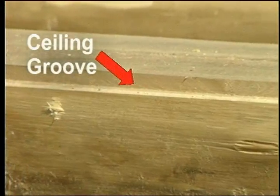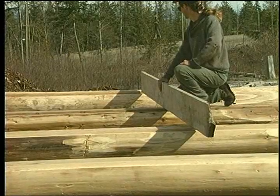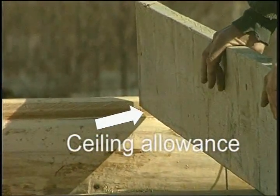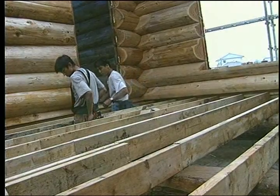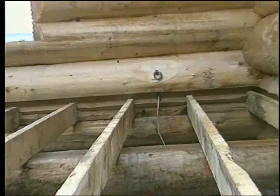In this case, you would cut a wider recess at the plate log and cap log to accommodate dimensional joists and ceiling, as well as the flooring. A recess for the ceiling material can be dadoed into the edge of the beam or a furring strip secured to the top. If the ceiling is to be decked with a planking material such as 2x6 or 2x8 tongue and groove, it can be an advantage to make a groove for electrical wiring. If you are going to run additional joists, the wires can be run between these.